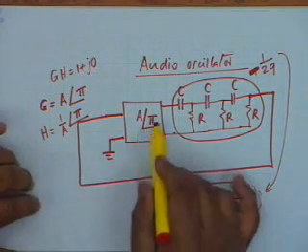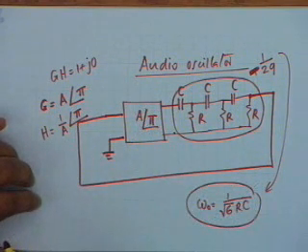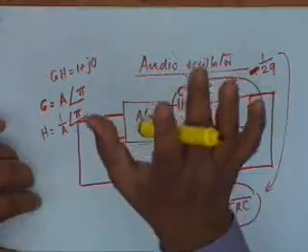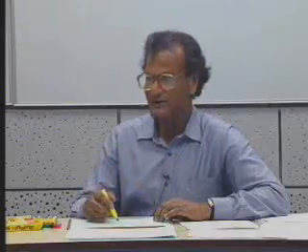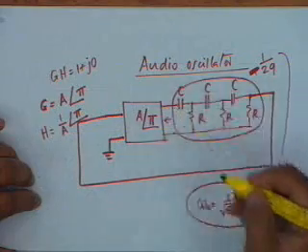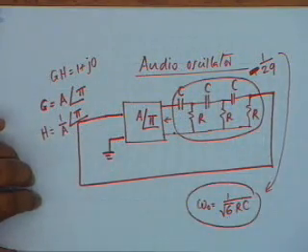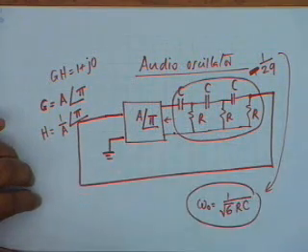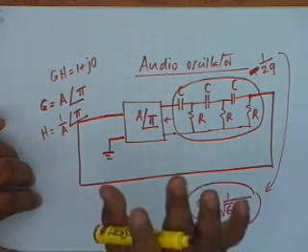Therefore, can you tell me what gain shall be needed for the amplifier? 29, right? So an amplifier, if you design for a gain of 29, a single stage amplifier which gives a 180 degree phase shift, then you connect this, and that will be the story. Unfortunately, if you use a single transistor, the output resistance of the transistor is not 0. Here we are assuming that the output resistance is 0, the amplifier is ideal, which is not the case.